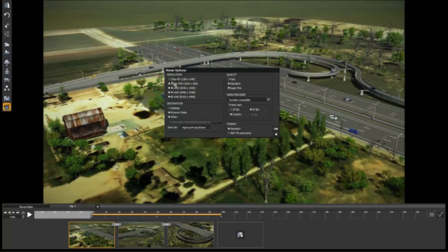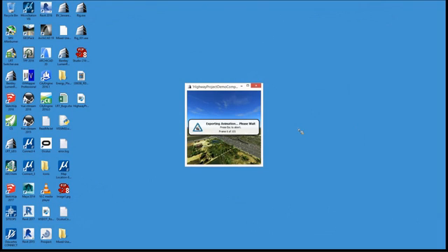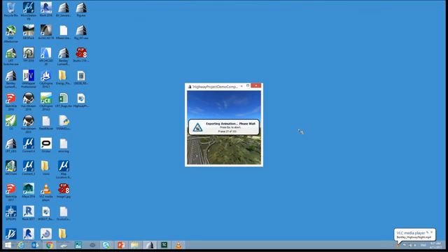So I'm just going to create one here really quick. I'm just going to make it a very low res one. I'm going to make it like 5. I'm just going to do 10 frames a second. Okay, so I'm going to say okay. So basically what it's doing now is it's creating all the frames. You remember that cross strip map that I showed before? This is actually what it's doing. So it's creating each one of those shots, top, left, bottom, right, and front, and then combining them together into this equirectangular image. And when it's done, you'll see a complete equirectangular video generated from this.